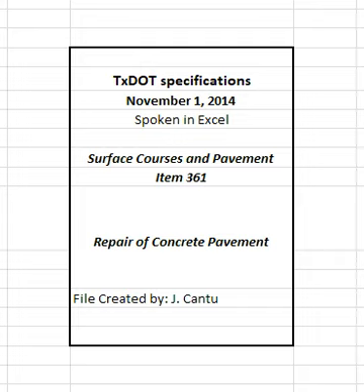Place tie bars as shown on the plans. Drill holes into the existing concrete at least 10 inches deep unless otherwise directed. Use a drill bit with a diameter that is 1/8 inches greater than that of tie bars. Clean the holes with a wire brush and compressed air to remove all the dust and moisture.